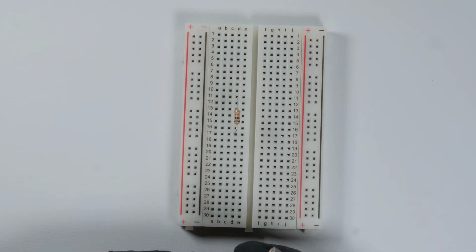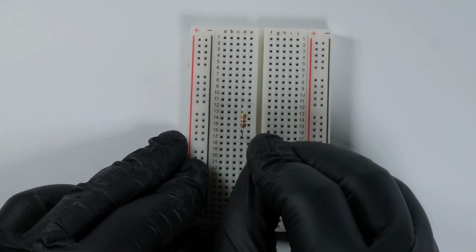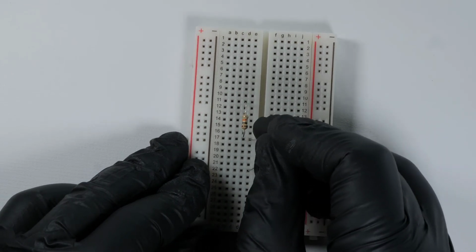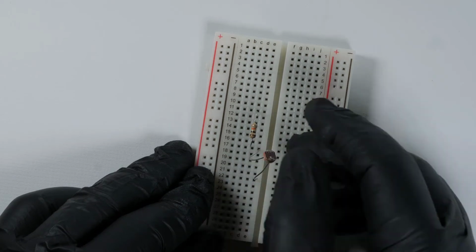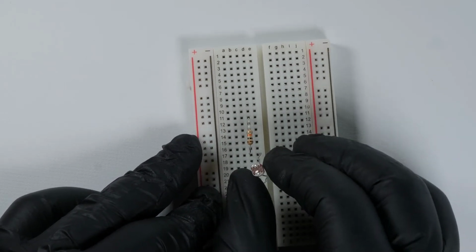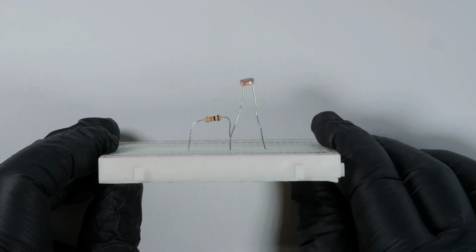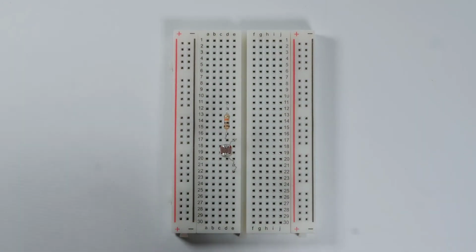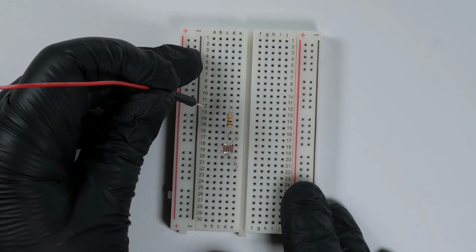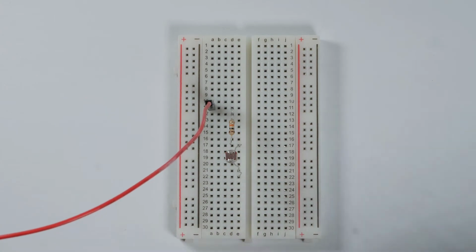Next is the photocell, which needs to be connected to one lead of the resistor and in a separate empty row on the breadboard. Once that's securely in place, double check and make sure that the leg of the photocell and the leg of the resistor are indeed in the same row, and then grab jumper cables to pull a 5-volt and ground signal from the Arduino. The 5-volt signal should go into the resistor, the ground signal should go into the photocell.